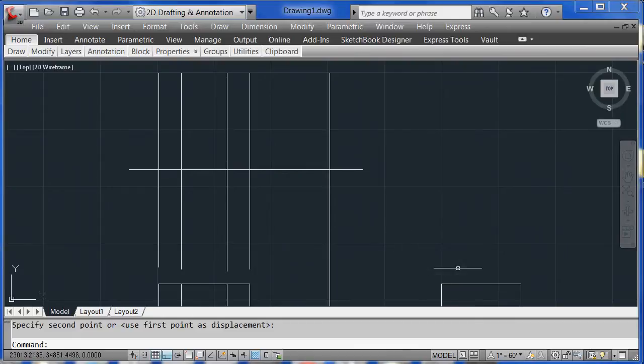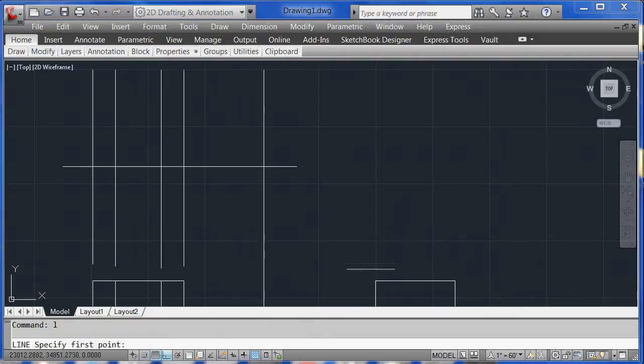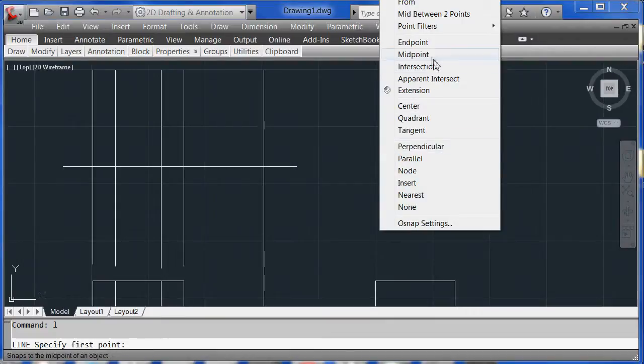Now let me show you a drafting technique that works in manual drafting as well. We can use it in AutoCAD to get our width. Now our width is fairly basic. It's 3.5 units over, and all I need to do was offset this line over. If you remember the first couple of weeks, I showed you the up, over, and then back down technique on how to bring some of these dimensions over to other views. So what we want to do is have this bottom line and this side line meet. So what I'm going to do is create a line.